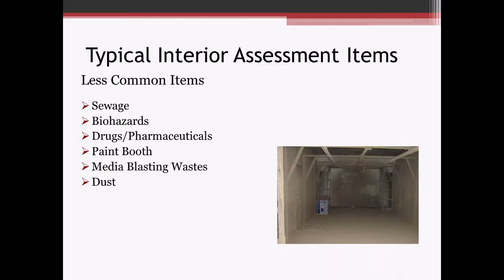Paint booths might have some residual contaminants in those types of facilities. Media blasting waste, so if you're doing sandblasting or other type of media, that waste may not necessarily be the sand itself, but what the sand removed might have some chemicals or contaminants in it that would need to be disposed of. And then dust could be a hazard, especially in some industrial settings where you've got an explosivity hazard with dust. So if you have a lot of dust accumulate in a facility, that might be something that you want to take on immediately and get out of there, so you don't have that explosivity hazard.